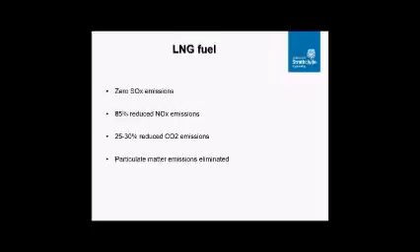This clean burn concept means that the quantity of air in the mixture of gas and air fed to the engine's combustion chamber is more than is required for all the fuel to be fully burned. Lean combustion technology reduces the temperature of the combustion process, and this reduces the amount of nitrogen oxide.